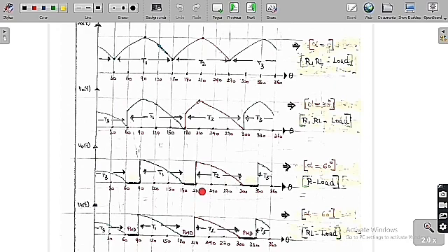Similarly, T2 is triggered at 210. So when T2 is on, V0 is equal to Vbn. Again at 300, Vbn wants to be negative. Whenever Vbn is negative, I have already told you V0 cannot be negative for R load. But actually it won't happen, because if it is negative, the current is also negative, and thyristor current cannot be negative. Because of that, it will be open, or simply we can say that all thyristors are open in this period, 180 to 210 degrees.